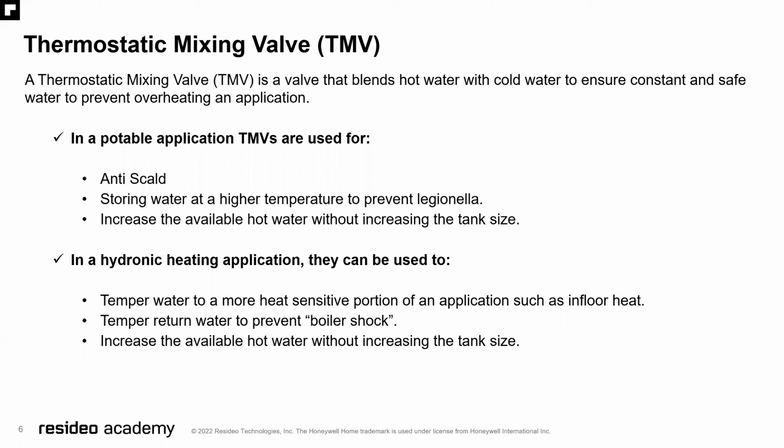In hydronic heating applications, they can be used to temper water to a more heat-sensitive portion of an application, such as in-floor heat, or if you have a concrete slab with in-floor, to make sure you don't denature the concrete, to temper the return water to prevent boiler shock, and to increase the available hot water without increasing the tank size. As for how much a system can benefit from this virtual tank, where you're heating the tank higher than you normally would, but then introducing cold water to produce the mix, your sales rep can help assist with the calculations on that to see how much extra water you would get and what temperatures you need to set it to.